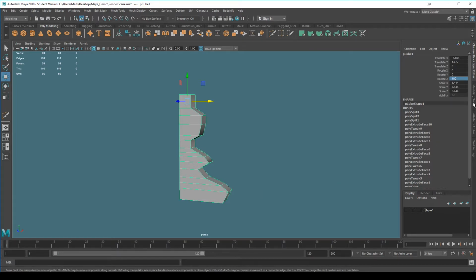So we'll notice as we model in the channel box, we're seeing all of these commands build up. The more you model, the more baggage Maya will have with the model. These are commands. It's very rare that you're going to want to come back to these. Notice though, if you do get rid of them, you won't be able to come back. But at certain points, when you decide you're happy with a model, you just hit Control S to save.